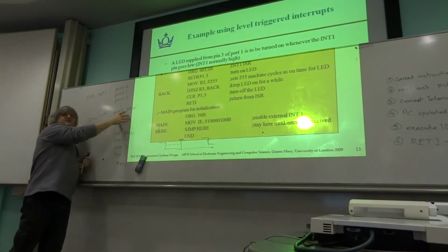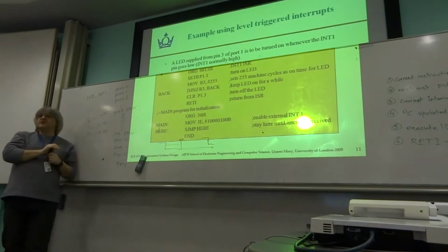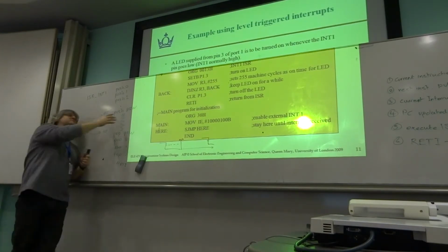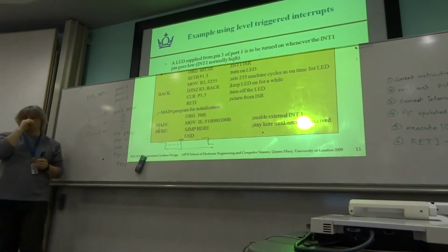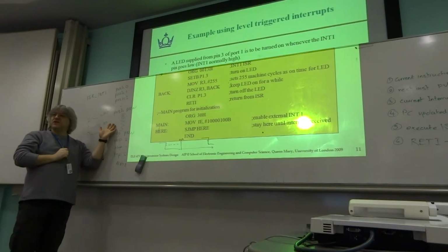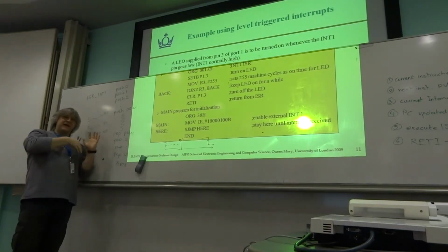The nice thing about doing this kind of thing, yes, it makes your interrupt service routine bigger, but you can rest assured that whatever you do in your interrupt service routine, it isn't going to mess up the main program. If you don't do that kind of thing, you've got to be very, very careful you're not fiddling with the same registers that the main program's fiddling with. And that might include things like the carry flag and so on.